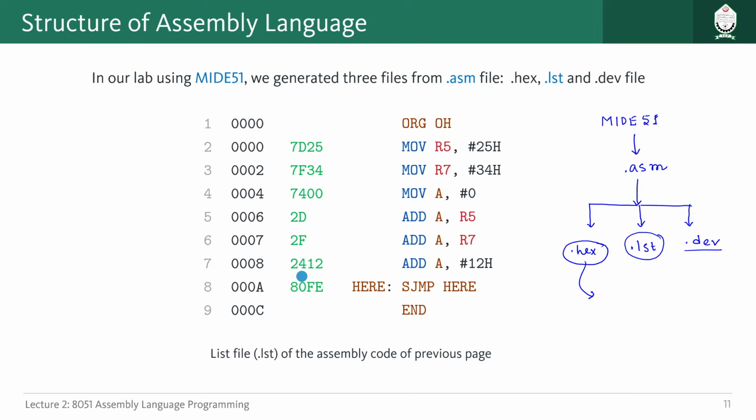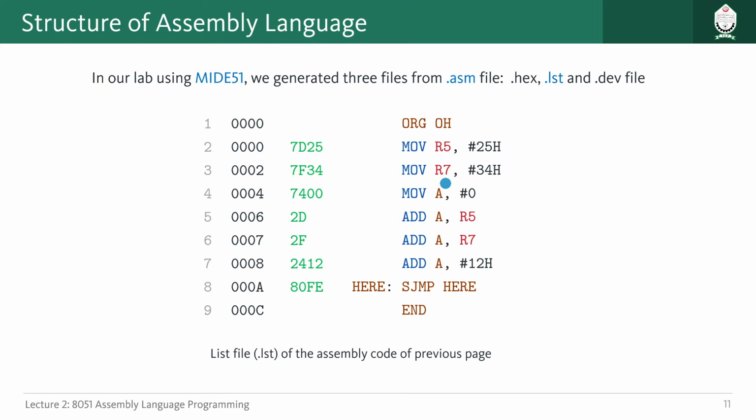So now, what is opcode, what is mnemonic, what is operand? Let us try to understand that, right? Let us look at these two lines here. This is the assembly language and this is the corresponding machine language of this particular line. For this portion, the first two hex digits, 7F, this 8-bit portion, is actually called the opcode.